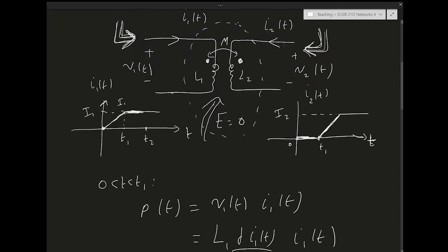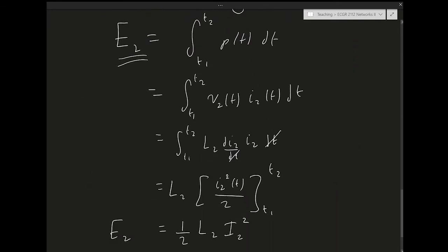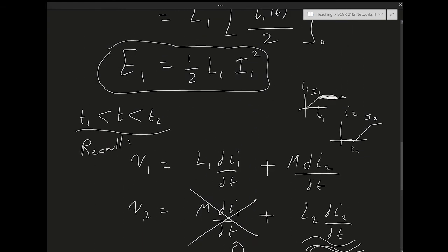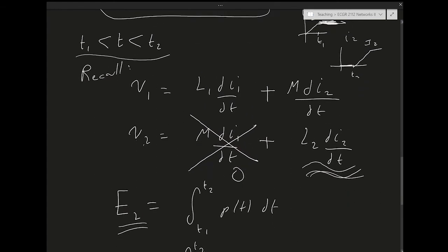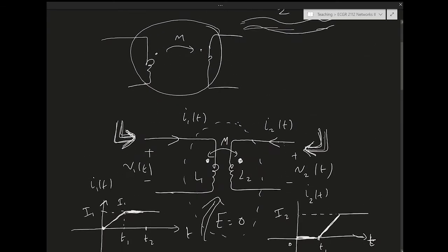So although I1 is not changing, let me go back to this equation. There's something else I can see here. Although I1 is not changing, this is 0, right? So this is also 0. I1 is not changing during this period. I still have this term here that's a function of I2 that changes V1. And V1, even though I1 is constant, when V1 changes, that changes the amount of power going into the system. So you have extra energy during period 2. You don't only have energy coming from circuit 2, you have also energy coming into the configuration from circuit 1.